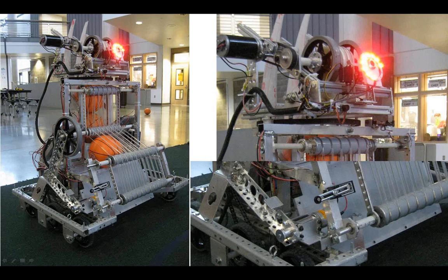They have box aluminum, that rectangle aluminum. You can see some up here. You can see that they've elected to weld. You don't have to weld parts, so don't flip out if you don't know how to weld. A lot of times you can bolt them together as well. You'll come up with a way to do that. There's a lot of bearings and a whole bunch of things that maybe you have never seen before, but all of these sorts of parts you can get from AndyMark or from local suppliers.